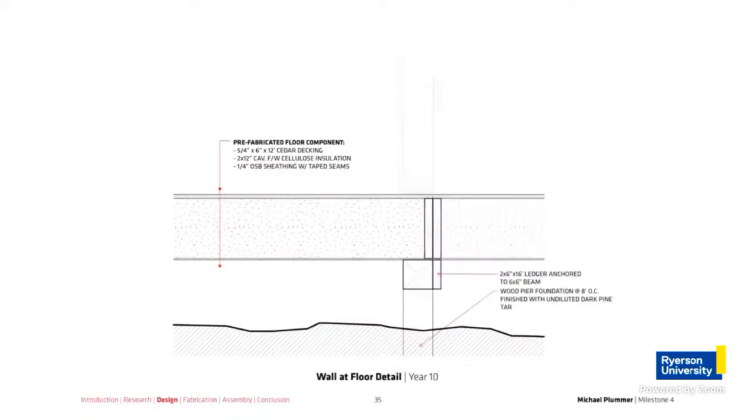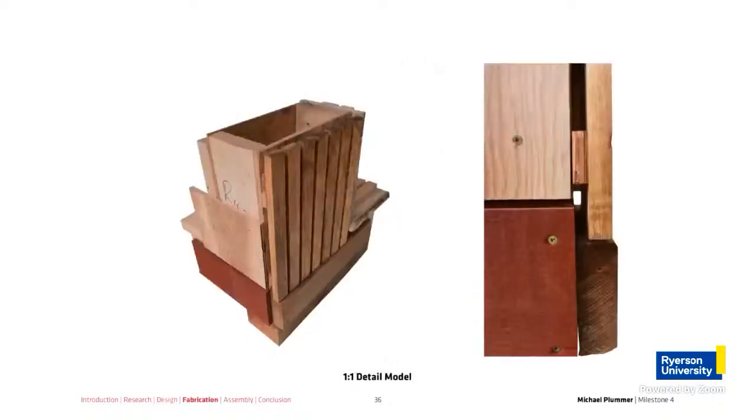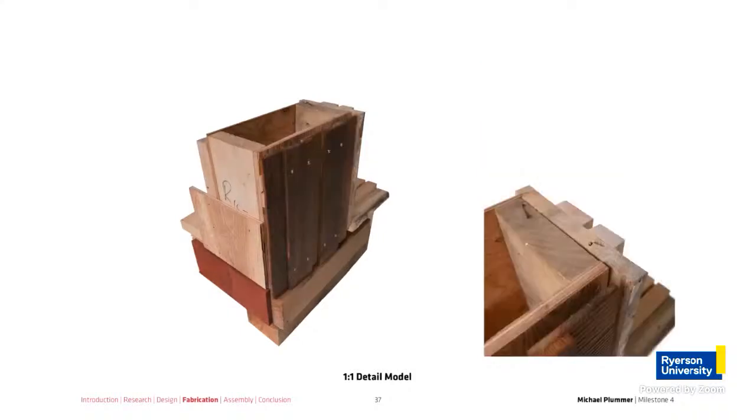The alignment joint between the base plate of the wall and the floor component serves to align the two components quickly and reliably. The components are assembled before the exterior cladding is installed, and then a French cleat anchor is used to hang the prefabricated cladding screen from the wall components. This allows the cladding to be removed in one piece for maintenance. The cladding panels can be removed, cleaned, sanded, and refinished much more safely and regularly. This prolongs the life of the exposed wood elements and allows the dweller to further participate in the dwelling process throughout the building's life.